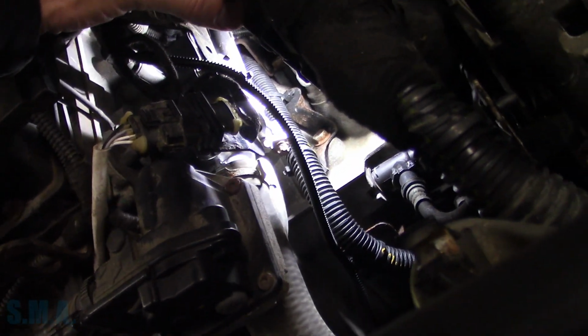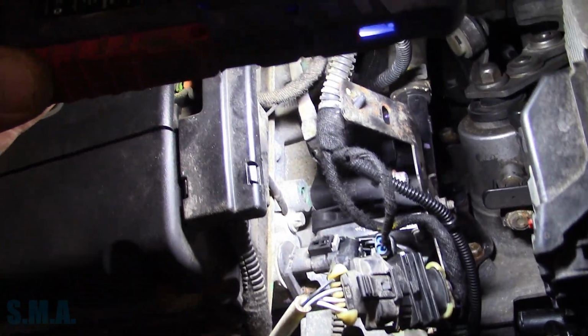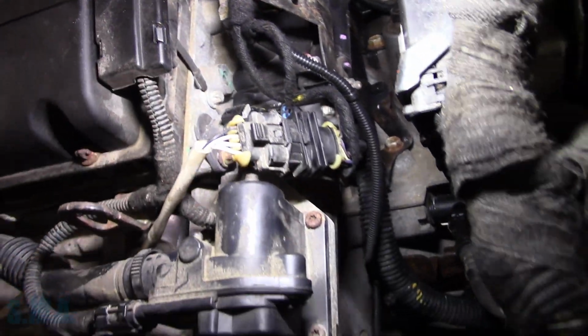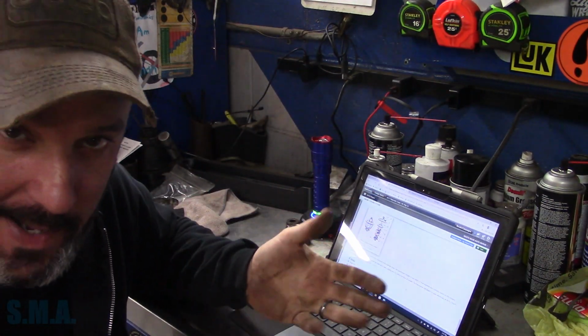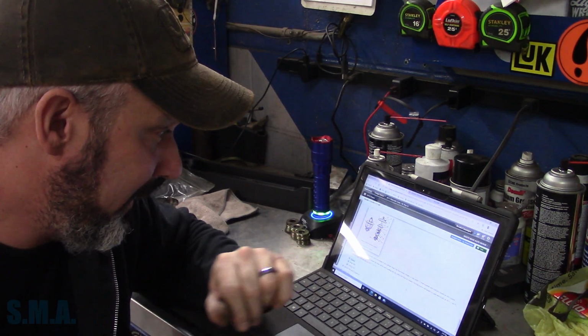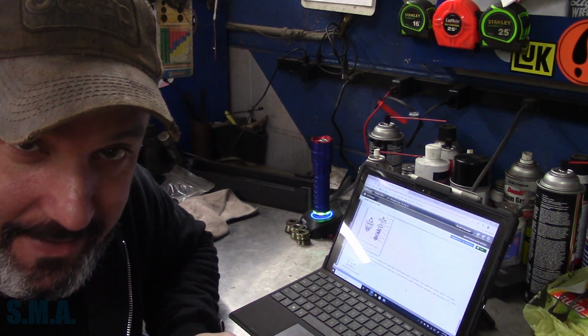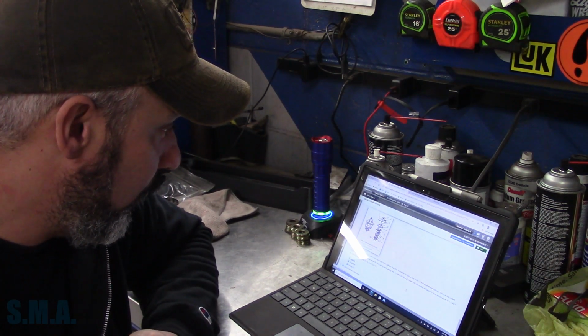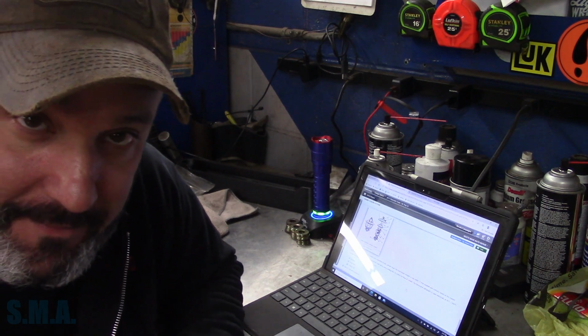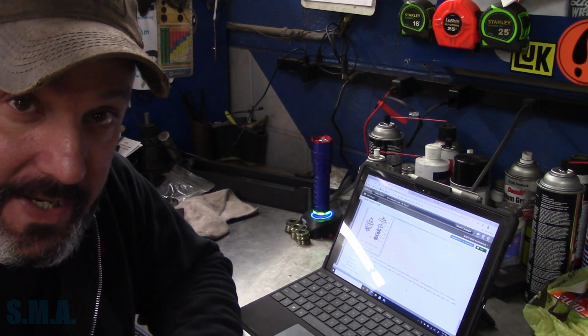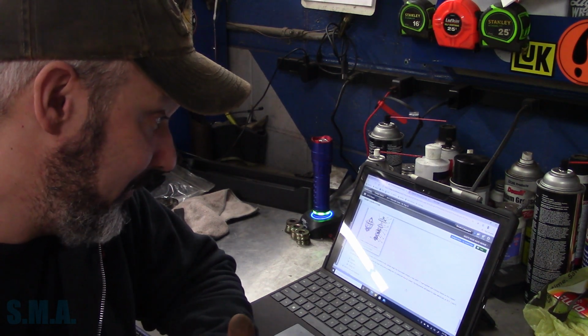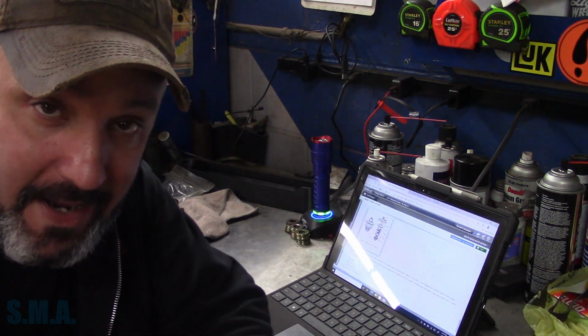Our coolant level's full. We've got everything cleaned up down here. I got a mirror and I shined it down under that housing. I don't see any leaks. Everything looks good. In those regards, we should be good. So just doing a little poking here under the theory and operation. It says the thermostat will begin to open electrically at 194 degrees or 90 degrees C and will fully open mechanically at 105 C or 221, which is what I saw when I looked over there. Perhaps I missed it when the heater itself kicked on, or perhaps I didn't. Other than that, it's just your standard wax pellet thermostat.